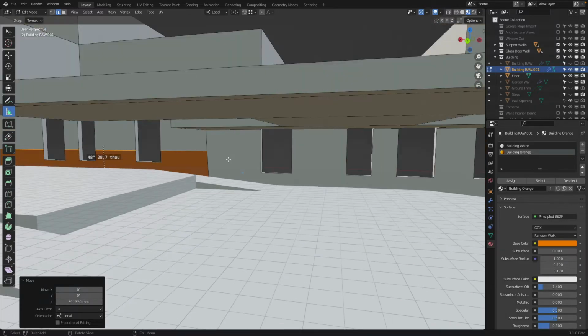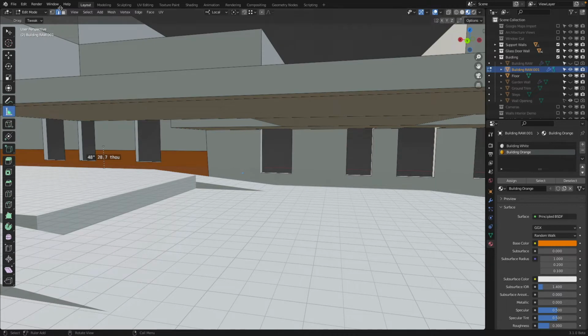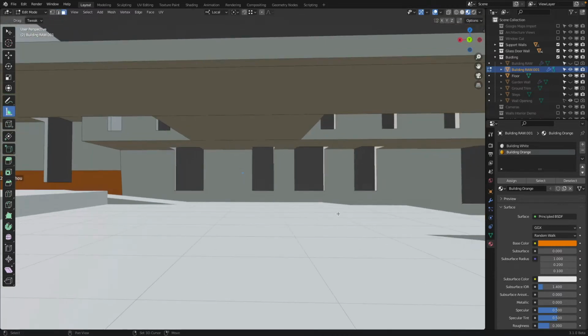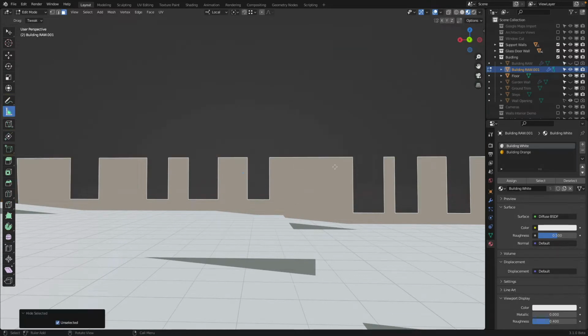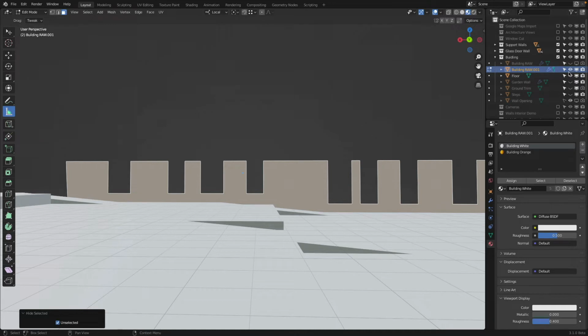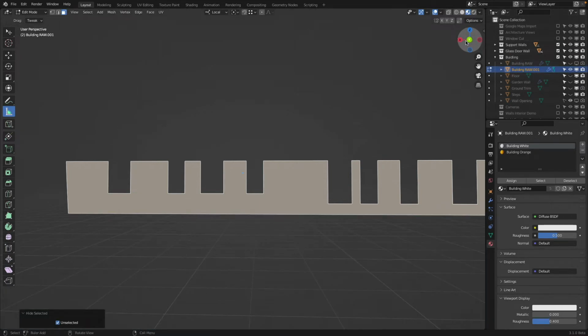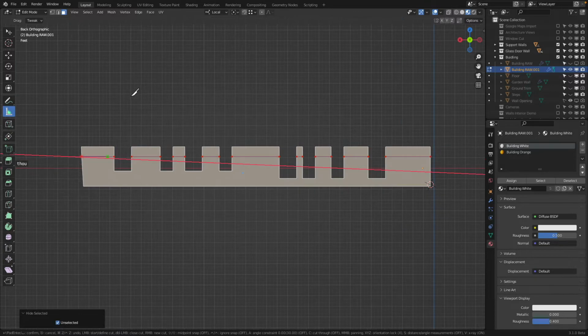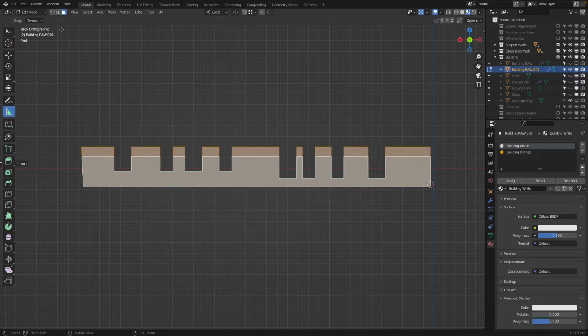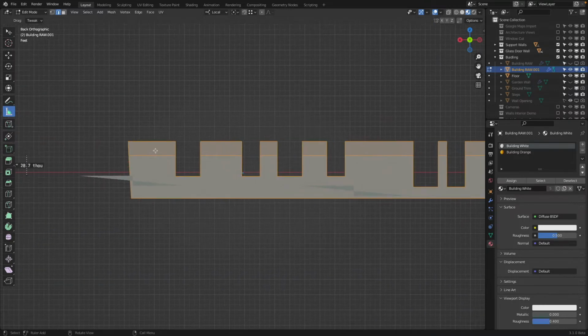Okay. So, but how do we do this now here on this wall? And then there. So again, I hide everything else, select this face, Shift H, hide the floor, go to this view, K. I simply slice really high on top. There we are, and enter. Thank you.